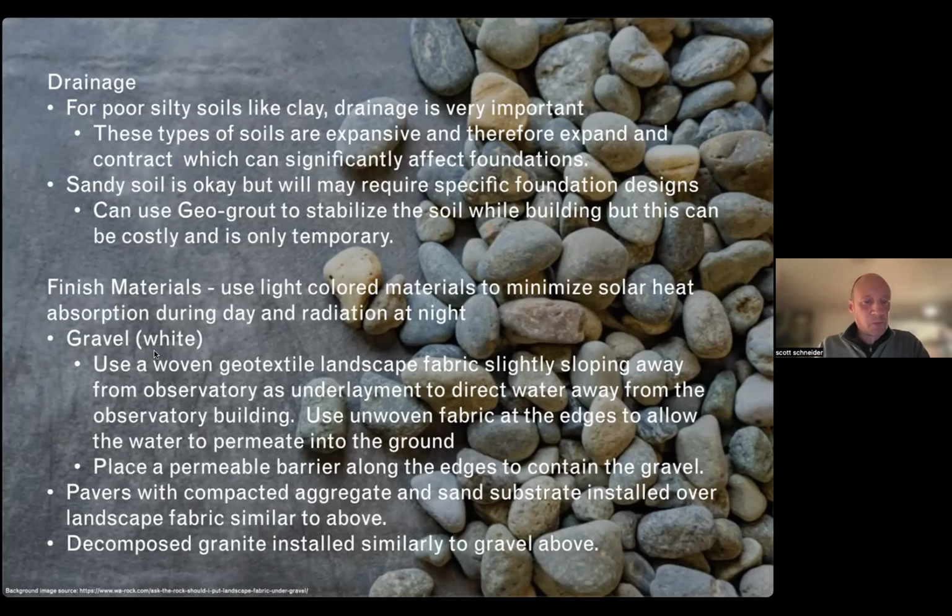You can also use pavers instead of gravel for more aesthetic reasons, but I think it's a little bit better to use gravel because it's more permeable, and with these barriers underneath it, it helps get water away from the building, from your foundation.